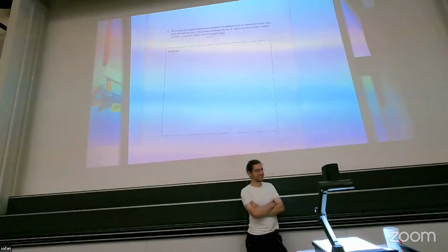But what happens is the address bit is 9 here, the output is 32. So this one is 512 words times 32 bits. And this one is 256 words, each 64 bits. They are both 2 kilobytes.